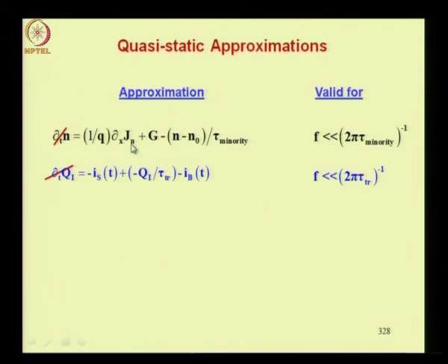When you integrate this, you get these two terms for the two limits of integration, the drain and the source. There is really no excess generation in the MOSFET. We are assuming such a condition because of light or impact ionization and so on. All these generations are neglected, so this term is not there, and this bulk current is actually a consequence of the generation recombination current that is coming by integration of this term here.